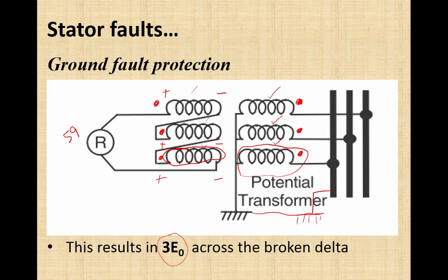So anywhere in the power system, whether that is a transmission line, generators, or any other part of the power system where the system is ungrounded, grounding can be detected with the help of this method. The three-phase VTs where primaries are connected in Y grounded formation and secondaries in broken delta, and we will observe voltage across the broken delta.